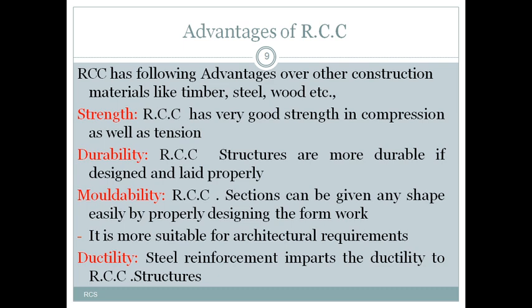Here, ductility means elongation of a member. When it is subjected to tension forces, the steel bar will elongate. This is very useful in RCC members because, as a result of the elongation, it will give enough warning before failure of the section.